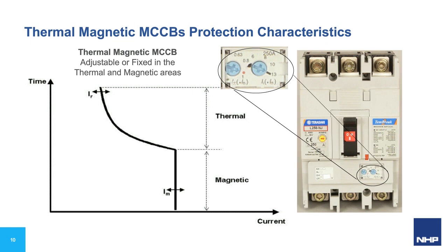This is of course heat dependent and proportional to current. It is sensitive to ambient temperature and will trip more quickly in warmer environments. The magnetic protection is provided by the magnetic short circuit coil, which at certain high current levels will force an internal ferrous shot pin out against spring tension to trip the latch mechanism.